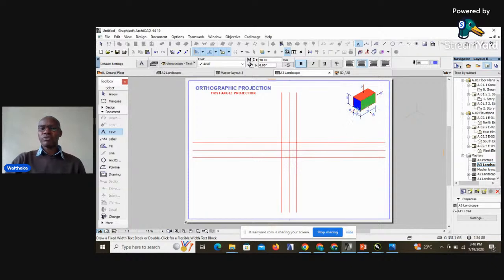Sorry, our end view, because it's on our left, will go to the right, and that means that our end view will be placed on this side of the Cartesian plane, because this is our right hand quadrant. The end view goes to the right because the one we are supposed to project is to our left, so we project it to the right.